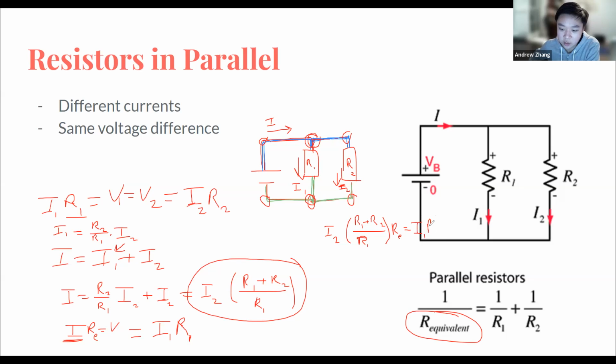Cutting a bit into this diagram, that's okay. Actually, I should use this instead. So this is I2 times R2. So it's equivalent, but we're going to be canceling out these expressions here. So I2 times R2. Then some simple algebra tells us we can cancel out I2, of course, and then we can shift everything over to the right to get RE is equal to R1 times R2 all over R1 plus R2. So this is our expression for R equivalent.